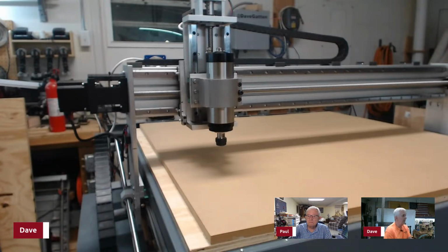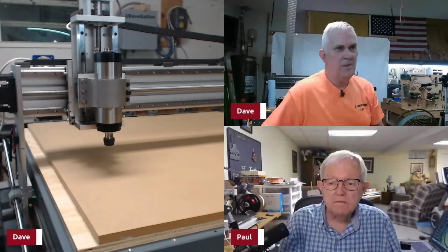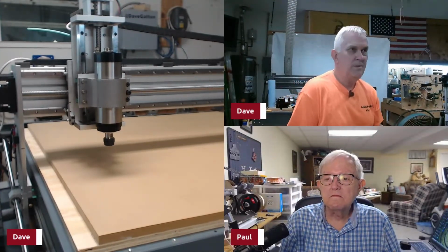It's currently set up with just 5 wires because it's not using reverse. Well, as I'm doing this, I want to go ahead and wire it up to do reverse, because you need reverse if you're going to use a rapid change ATC. You need to go forward and reverse. So I'd like to have one of those one day, but I figure while I'm at it, it's only one more wire, one more connection. So I'll go ahead and make that up so it's doing that too.